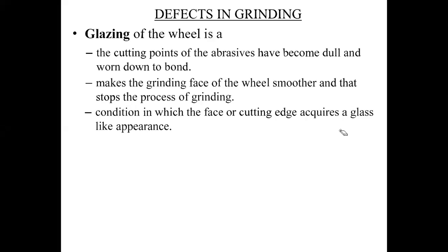In that grinding wheel, these abrasive particles are embedded, right? So very small particles are there. When you expose these small particles to very high force, acting repeatedly, after some time the sharp edges come out of the grinding wheel and fly away. When these sharp edges wear out, the surface reflection changes. This change in surface reflection, where the surface becomes dull, is called glazing.